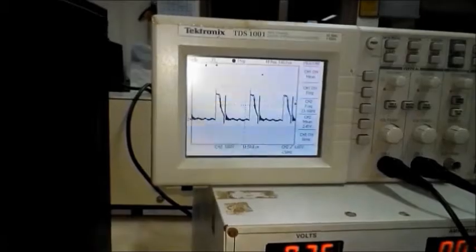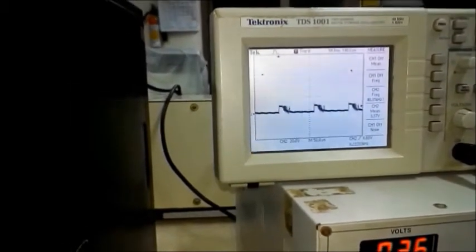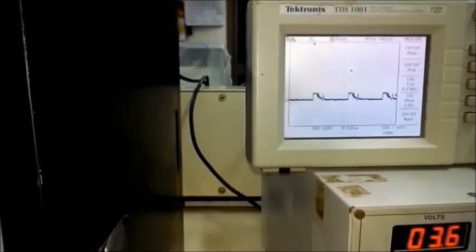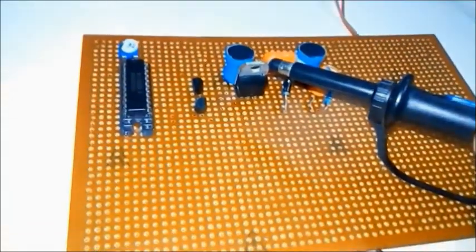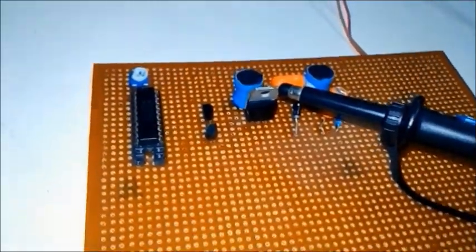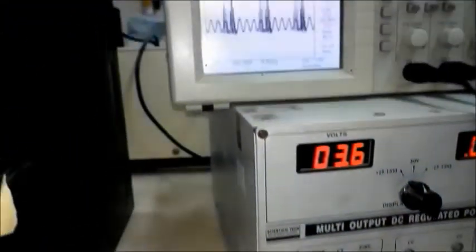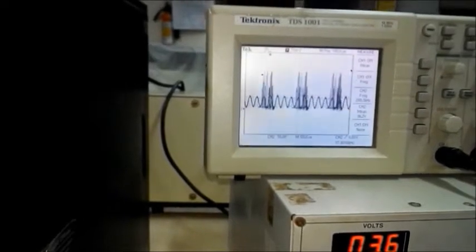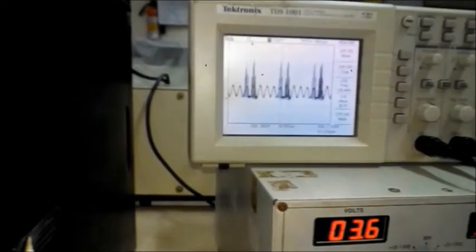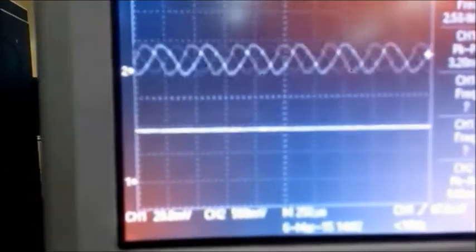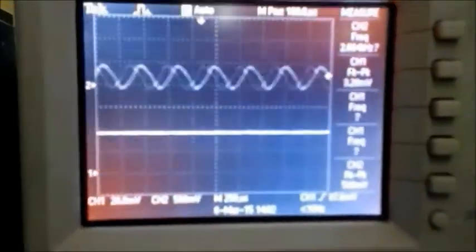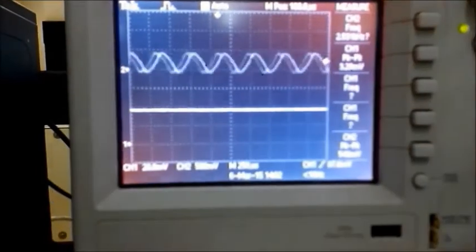Now what we see is the PWM output. This is the output used to buck or boost the signal. This is the intermediate Darlington pair output. This is given as a switching signal to the buck boost converter. Here what we see is the final DC output voltage which is obtained across the capacitor and is given to the receiver battery.